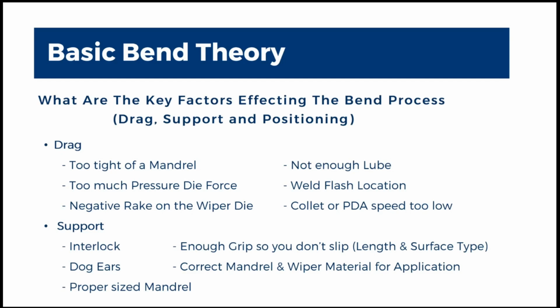The main components affecting support are interlock, dog ears, proper sized mandrel, enough grip so you don't slip, which is the length and the surface type of the grips, correct mandrel and wiper material for the application.